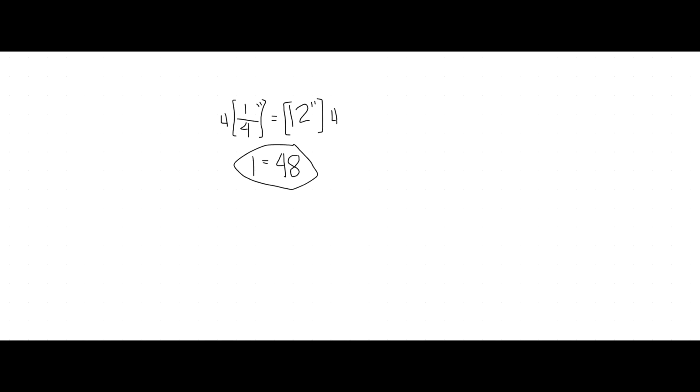And then for the text size, if you were to measure the size of the text on a piece of paper in paper space, it is 3/32 of an inch. Okay, and so then if we multiply this whole thing by our scale factor of 48, then what do we get?